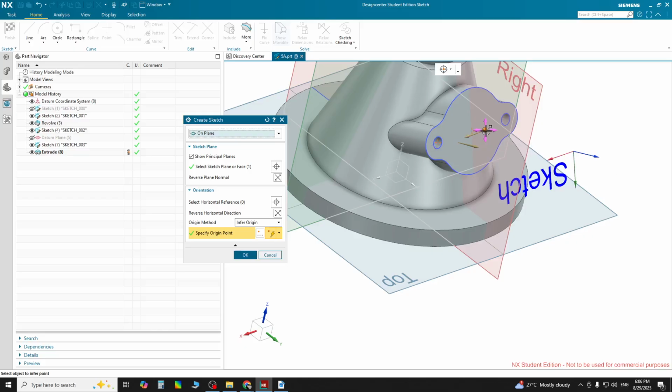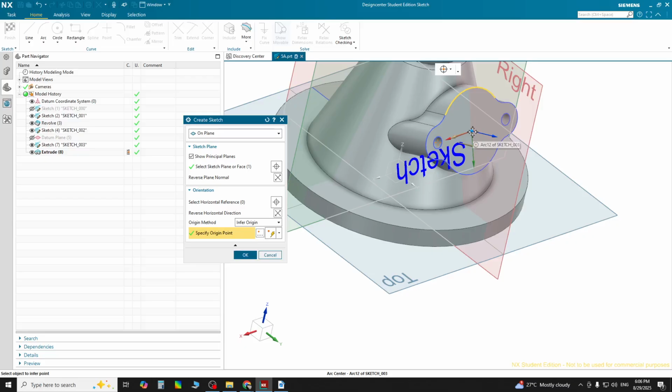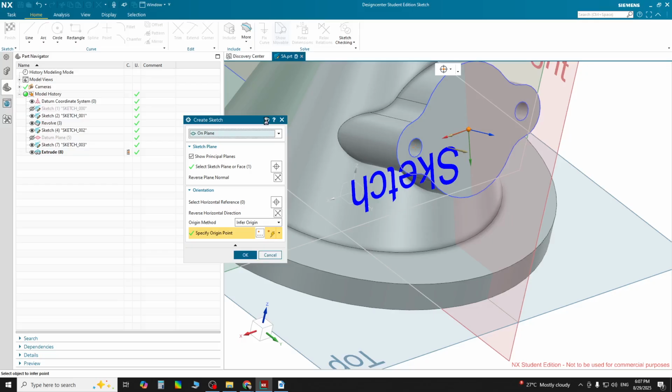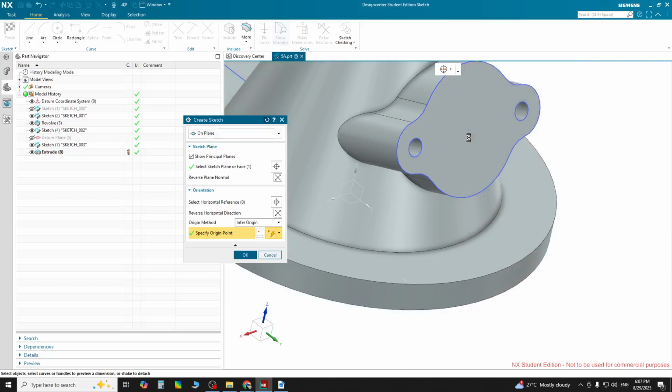So you click on that and keep your cursor on that circle boundary, then it will show you the center point. At that point you come to the center, and you are able to place exactly on the center point. This way you have to do carefully, as a little deviation causes error. So I repeat this, reset this, and follow the default center origin.